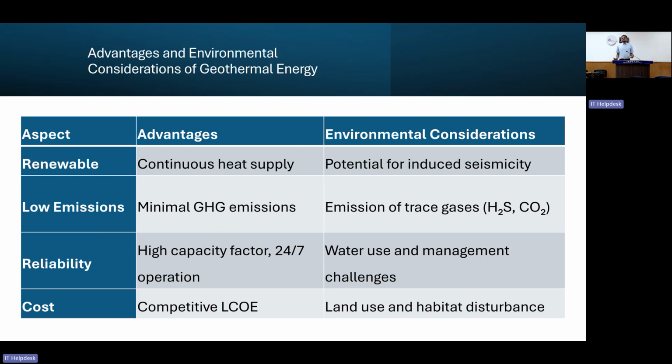However, there are certain advantages and environmental considerations related with geothermal energy. Although it is renewable and produces heat on a continuous basis, it has the potential of inducing seismic activity. Although there are minimal GHG emissions with the processes, there are some emissions of trace gases, which are environmental concerns, like H2S and CO2.